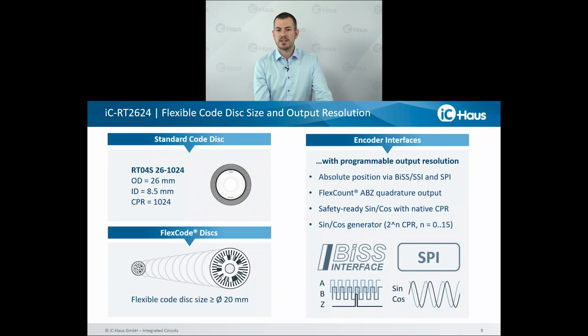Another cool thing about this sine cosine generator, as it uses the absolute position to generate the sine cosine, all the corrections that are applied to the absolute position also apply to this sine cosine output here. So it's quite precise and accurate as well.